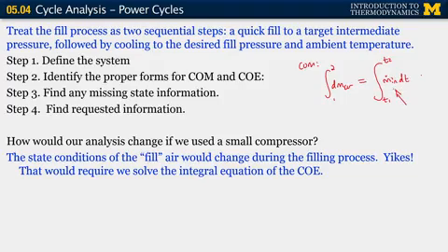And for this, you'd say, well, let's take the draining tank example. There, you would expect the mass flow rate to decrease as a function of time, probably exponentially or asymptotically. So you might imagine the mass flow rate doing something like this as a function of time. And we would have to decide, before we did our analysis, where am I on the slope? What's the magnitude of the initial mass flow rate? So this would be at the start of the fill, and this would be the mass flow rate at the end of the fill.